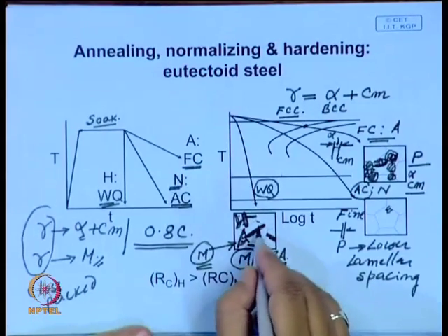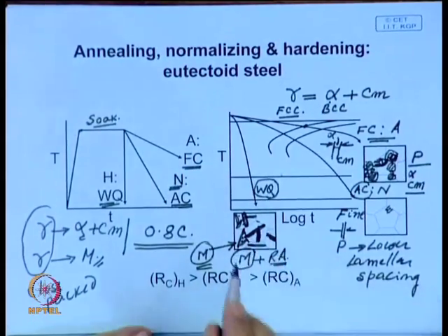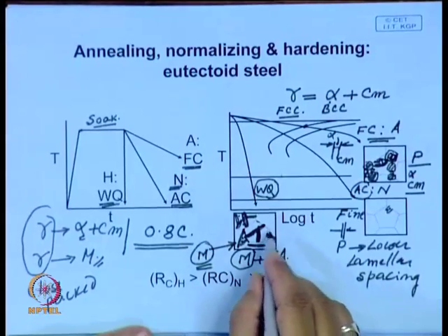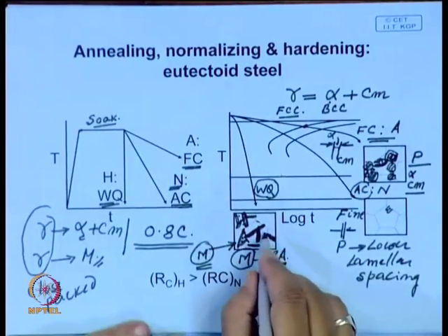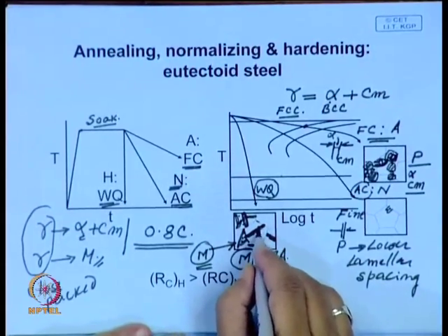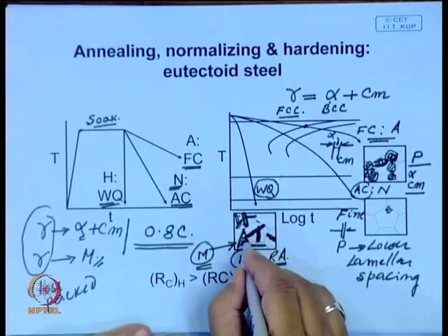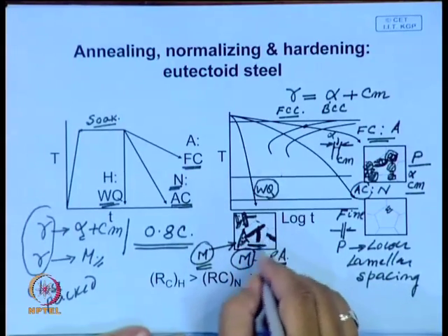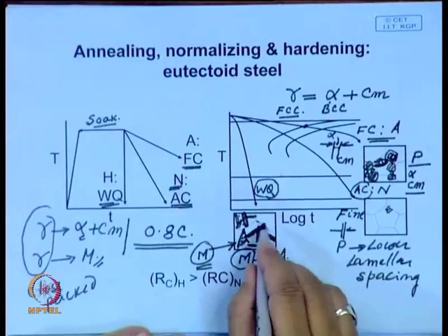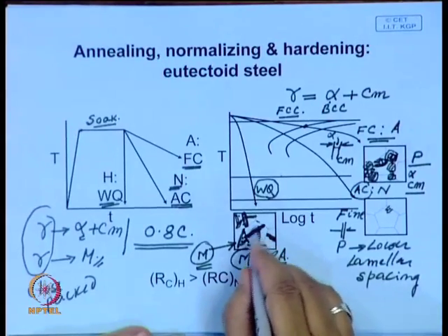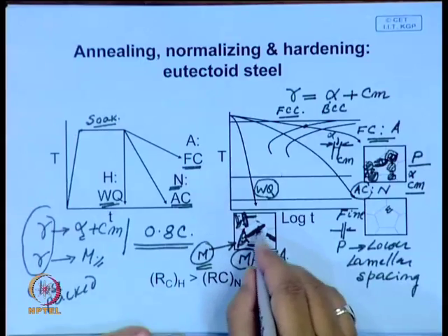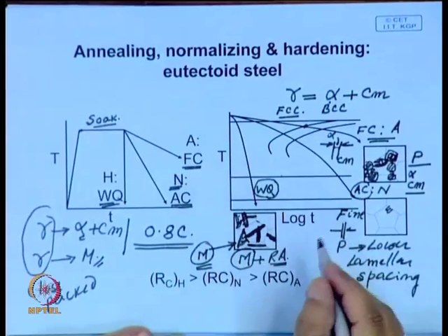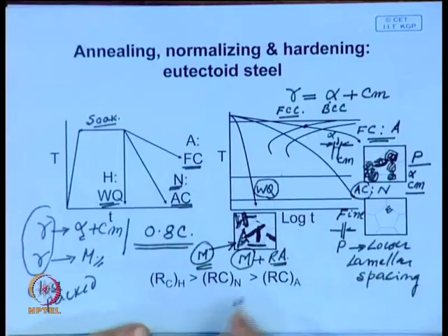But if you temper it slightly, as we will see, they etch very well and you can see this structure even under an optical microscope, but not the final details within one plate of martensite, because the level of resolution needed is in the nanometer region, which is extremely small. So, you need an electron microscope to resolve the structure within the martensite plates.